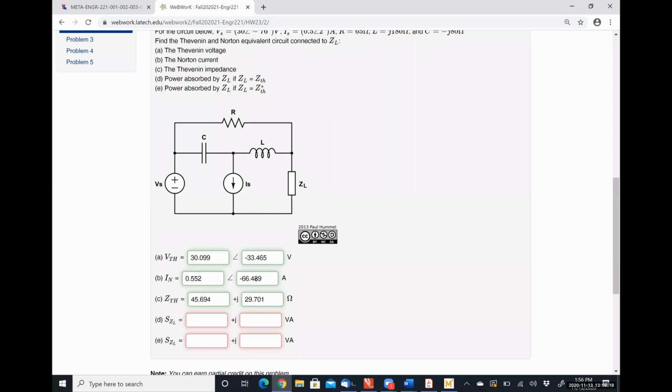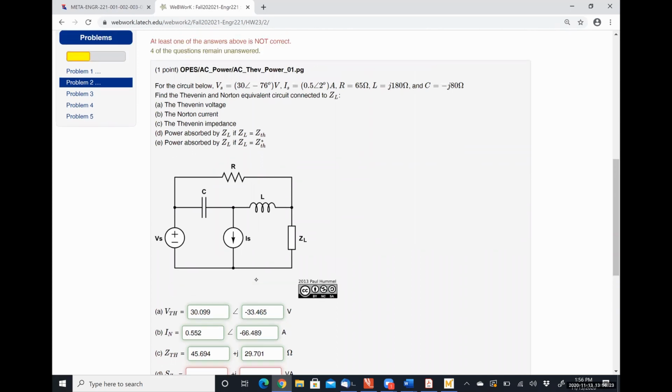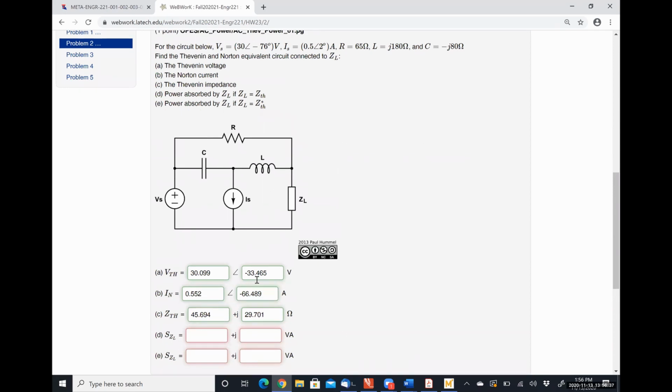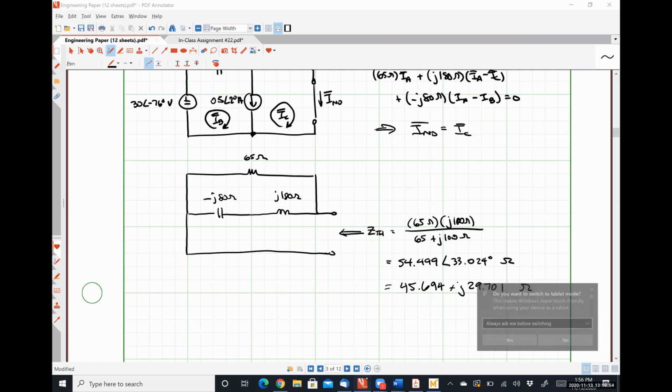Another thing that could potentially trip you up when trying to work this problem with your numbers is the fact that the quantity Vs and the quantity Is are not expressed as RMS values, right? But our complex power relationships are based entirely on RMS values. So let's circle back around to this one. So this should scroll up hard.